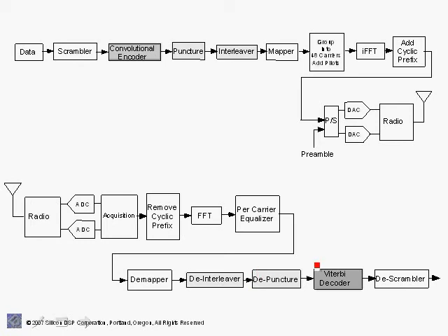As far as the Viterbi decoder is concerned, those bits would be in random locations, and of course the Viterbi decoder is very efficient at correcting random bits. So for forward error correcting coding to be effective in a wireless digital link with fading multipath channel, it is very important to include the interleaver and de-interleaver process. We will discuss the interleaver and de-interleaver in detail to show how this is accomplished, where a bursty error will not happen. In fact, if a carrier is wiped out, the actual bits that are affected would be in random locations such that the Viterbi decoder can correct them.